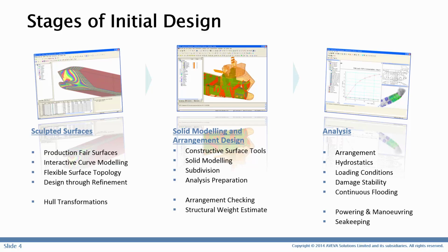This can do a lot of reports on your arrangement, starting with some simple hydrostatic calculations such as form calculations and cross curves. You can then move on to loading conditions, onto damage stability, both deterministic and probabilistic. You can go as far as doing continuous flooding simulations to look at what happens in this situation if you're grounded and you're needing to pump water out of the vessel. There are also a range of hydrodynamic analyses; powering, manoeuvring, seakeeping and dynamic positioning are supported.